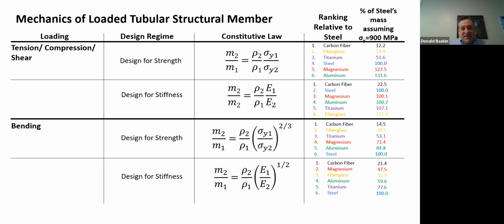It's the same thing for racing cars, like Formula One. Formula Ones are made out of monocoques. We'll talk about that later, but they're very directional. The monocoques are designed to be loaded in very specific ways. And if anything goes wrong and you get T-boned by another car, you're toast. The thing fractures all over the place. So it's really difficult to get isotropic properties out of carbon fiber.